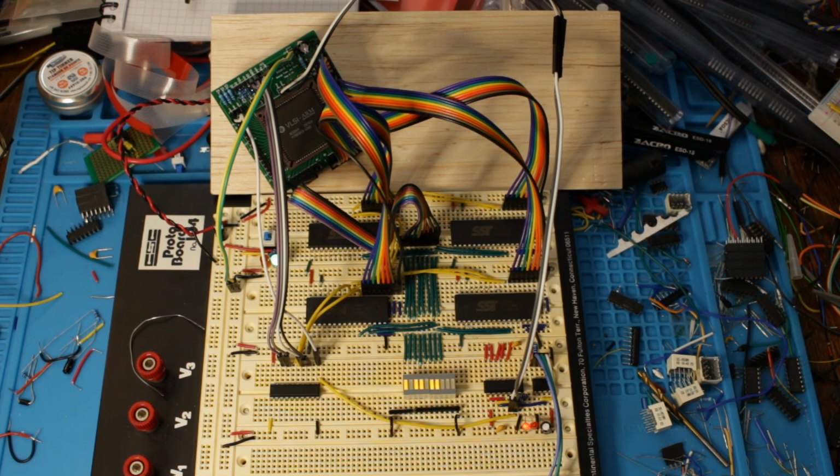The other thing on my mind is just that this arrangement of EEPROMs is quite inconvenient, as I said. I've got some scripts now which separate the linear stream of bytes into a ROM image for each EEPROM, so that's not a problem. But it is quite annoying having to take every single EEPROM out, put it in the programmer, program the right image into it, not get the wrong image into it, and then put it back in the breadboard.